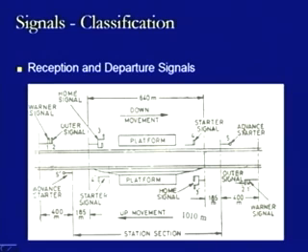So, from block section to station section, when the train is coming, a signal is provided here, and this signal is known as the outer signal. As we see in this case, there are two signals provided on the same signal post. There is an outer signal which is of the nature of a semaphore signal, and that is why it is provided at a higher side of this post, whereas there is another signal, a warner signal, located below this semaphore type of outer signal. These two signals in combination are provided at this location.